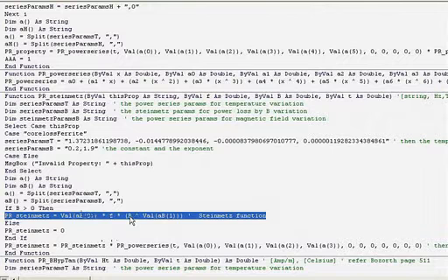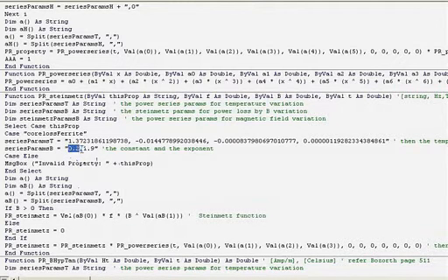You can see I'll highlight now the two parameters for that function. There they are, and I obtained those from the Snelling book, where he stated that he experimentally determined those to be representative of the core loss for the power ferrites that I was using.